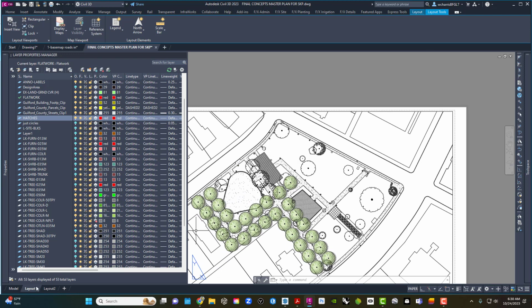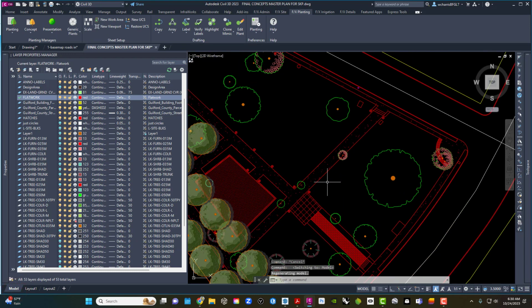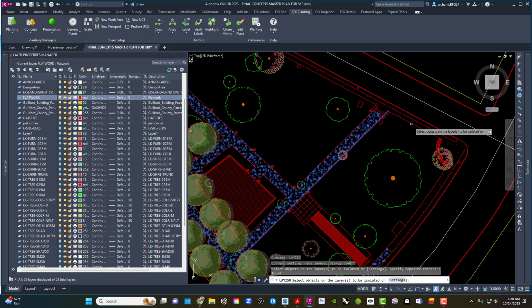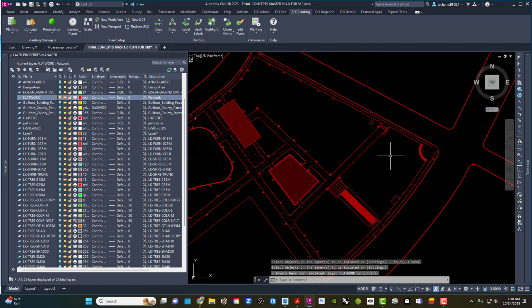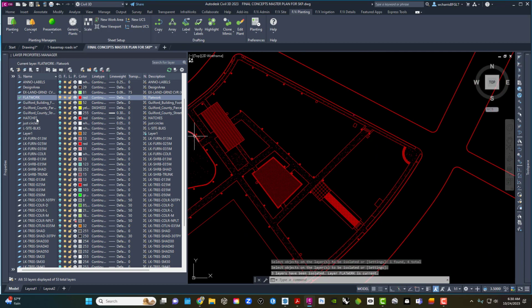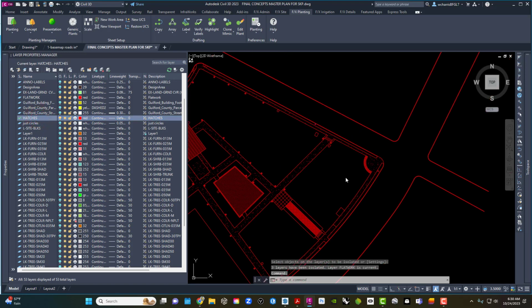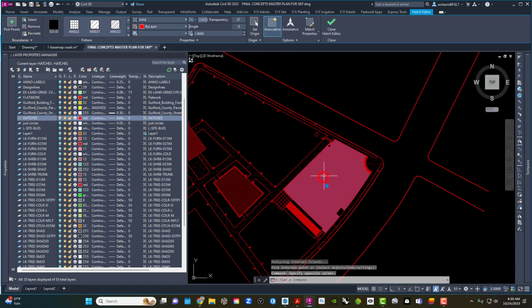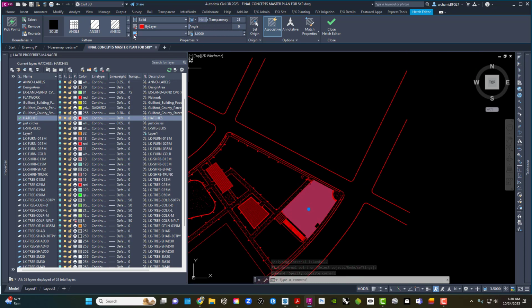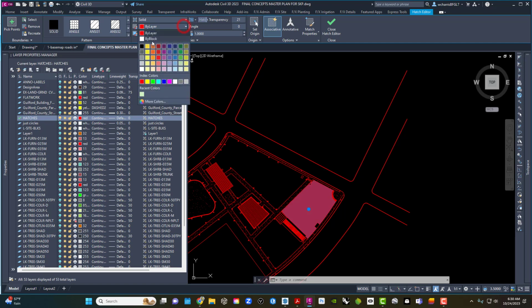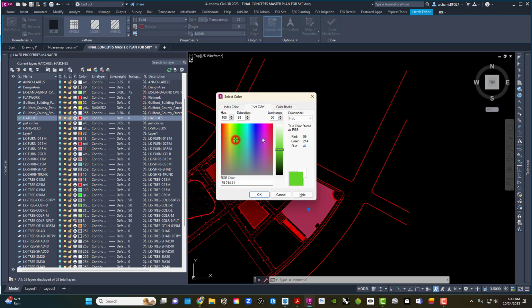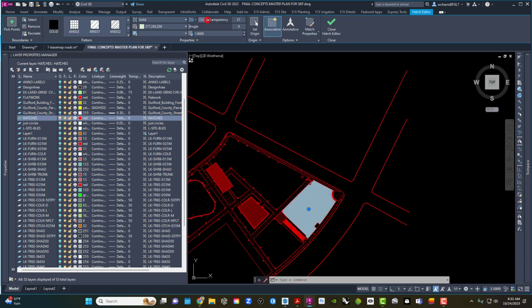Like I can go back into this and just do a LAYISO on the hatches and horizontal controls and flat work, and then put myself on hatches, for instance, and then do hatch this. Just want to show you all. I know hatches can be tricky, so I would probably honestly do this part in Photoshop, just kick out my flat work. But I can change this if I wanted to. I'm going to do more colors because it has to be a true color, and not a numbered color, or it won't print right. And make it green, and then maybe I knock up the transparency real good,